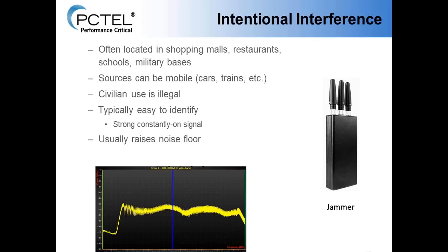So now I'd like to move on to radio propagation. We've got a good feeling now of what the sources of interference are. And if you look at radio propagation, you find that all spectrum is not created equal. So when you have higher frequencies, and this is approximate, say 1500, 1700, 1900 megahertz, they're typically more disposed to be line of sight and more easily reflected off of buildings and vehicles, with very low penetration into the building itself.